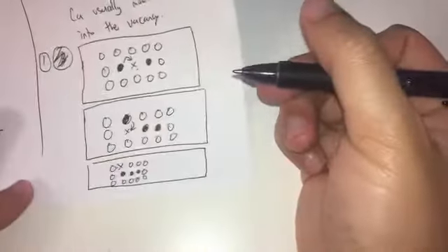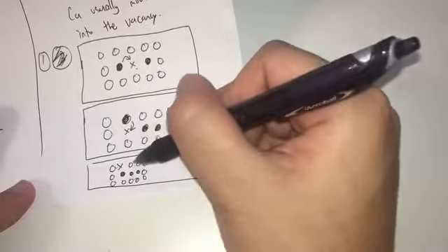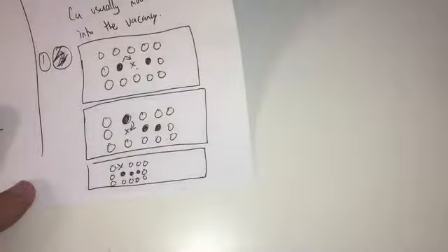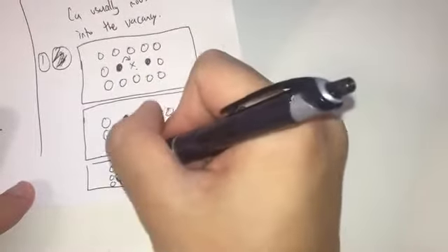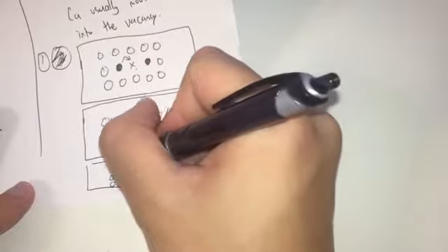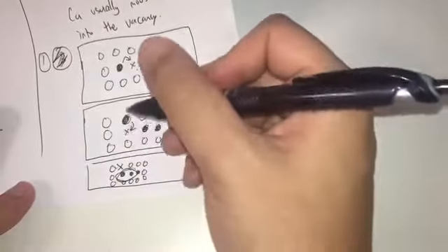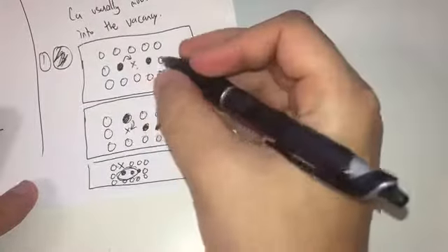So the vacancy will be here. For example, we will have these 3 atoms nucleate together. When these atoms nucleate together, they will not likely want to escape into this vacancy here, because now they're more tightly bound. Now they are in their own little metallic phase.